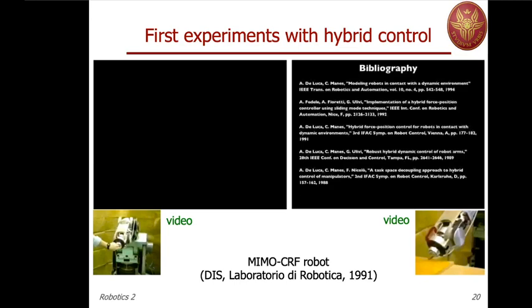So there will be some friction while moving, especially when we're pressing on the surface. So the tangent component of force, which is measured by the force torque sensor, is just discarded. We are regulating just the normal force, because on the plane, tangential to the path, this extra force opposes motion, but is seen as a disturbance to be rejected by the controller.